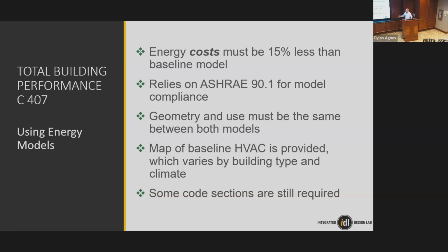And ASHRAE 90.1 will also guide you in terms of what your baseline HVAC is going to be. Depending on the software that you choose, whether it's OpenStudio or Code or even Revit, I'm pretty sure a lot of them already have baseline generators in them. So you can just click a button and it will follow the template and the requirements from ASHRAE 90.1, because it's a fairly common process. And it will generate that baseline building for you that you can then adapt.